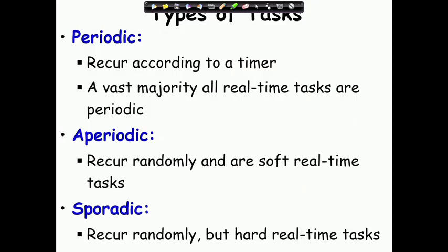And then we were looking at what are the different types of real time systems, hard, soft, firm real time systems, what are the examples of that. And now let us continue from there and let us see what are the different types of tasks that a real time system might have to handle. So, in a real time operating system, the tasks can be broadly said to be of three types: periodic, aperiodic and sporadic.